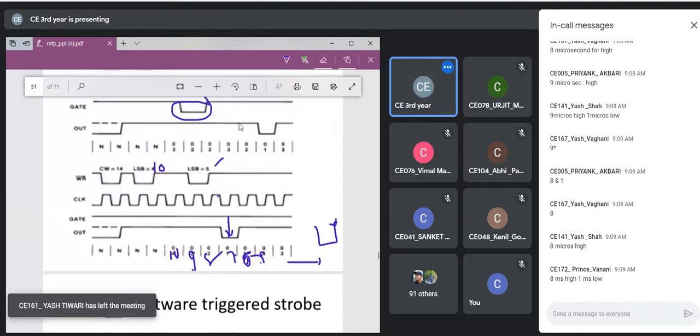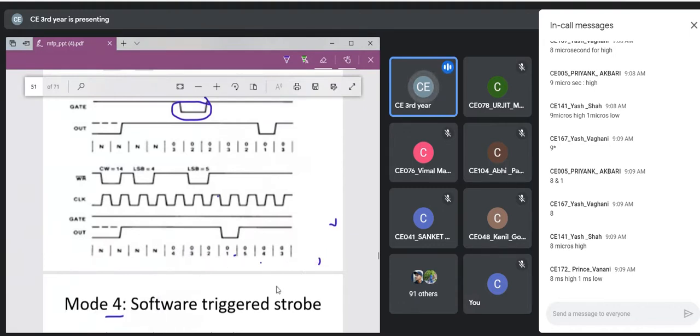Is it okay? So this is the interesting behavior of mode 2. Of course, it has to reload, but it will check the count once it completes its task of the current countdown. Before reloading, when it is completed, then it will reload the new count.